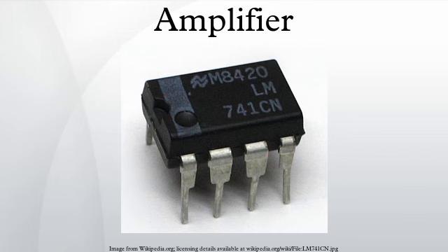Operational amplifiers. An operational amplifier is an amplifier circuit with very high open-loop gain and differential inputs that employs external feedback to control its transfer function, or gain. Though the term today commonly applies to integrated circuits, the original operational amplifier design used valves. Fully differential amplifiers. A fully differential amplifier is a solid-state integrated circuit amplifier that uses external feedback to control its transfer function or gain. It is similar to the operational amplifier, but also has differential output pins. These are usually constructed using BJTs or FETs.